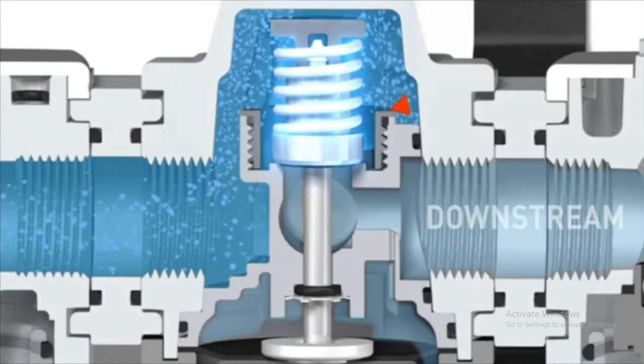It is also common to have a pressure gauge on a regulator so the user can monitor downstream pressure. Finally, in specific applications, such as air motors or pneumatic tools, a lubricator can be added to distribute a fine mist of lubricant into the compressed air to help lubricate downstream components.